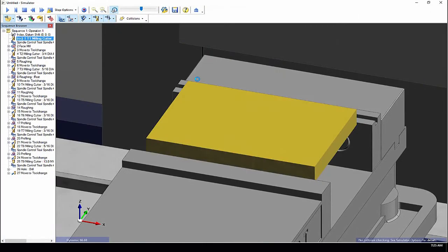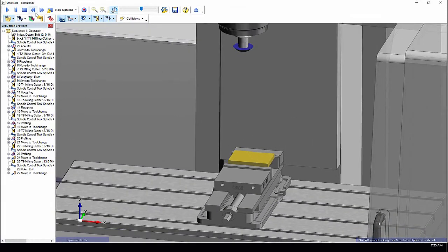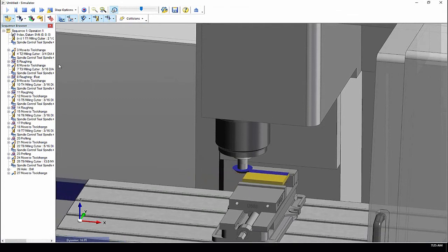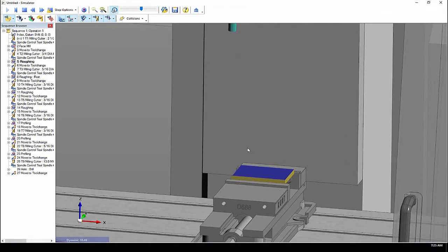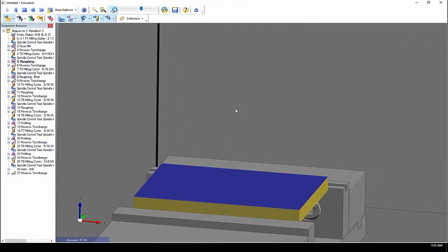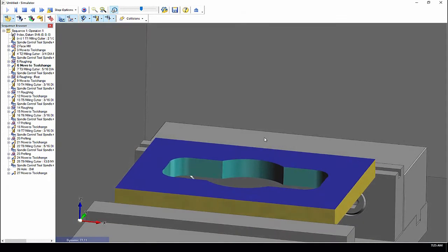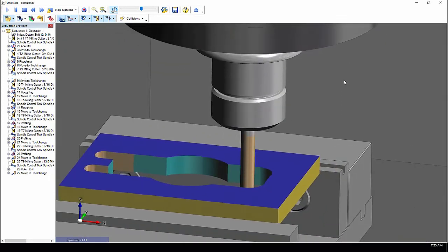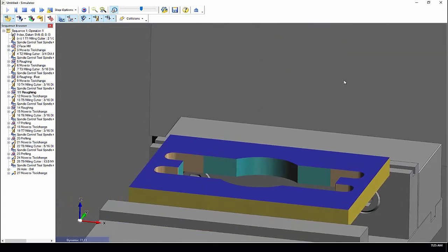Once the tool path is created for the part, a simulation can be reviewed as if it was on the machine. A true machine simulation can be achieved with machine kinematics. And as this is simulating, let's review the process. The part was loaded into the CAM system, and the required stock was defined and placed around the part. As an option, you may choose to define the stock with a simple interface allowing more interaction. This process is up to your own preference that will work for you.